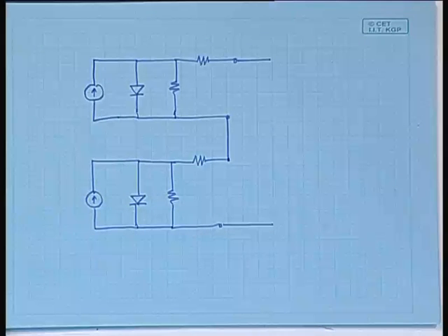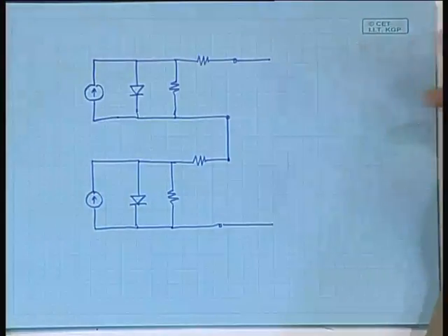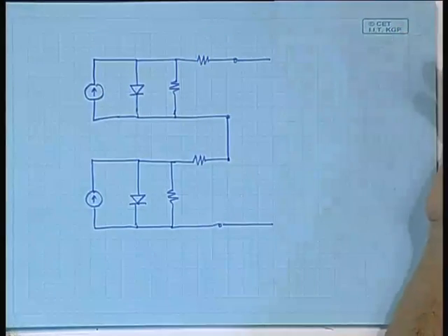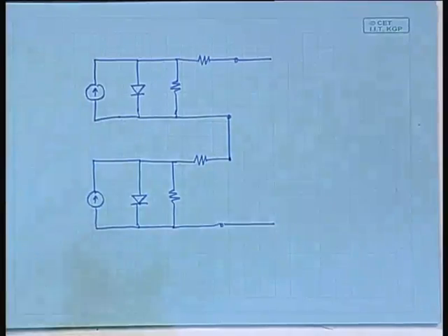Fine. Now, so far so good, no problem, the voltages will add up as all series connections do, the current will be the same as in all series connections. Supposing you connect two batteries in series, the voltage becomes double. But now notice that both these are generating depending on the amount of incident solar radiation, and it may so happen that one may be shaded, right. Say there are two panels and a tree's shadow falls on one, is possible.